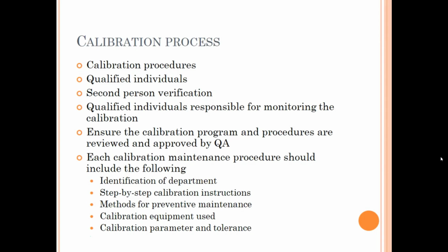You need a qualified individual responsible for monitoring the calibration program or the calibration system. You need to ensure that the calibration program and the procedures are reviewed and approved by the Quality Assurance Department.